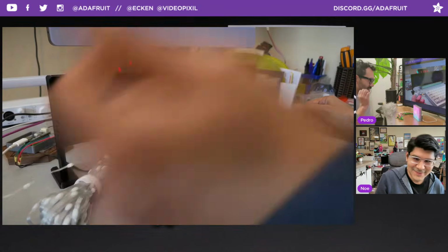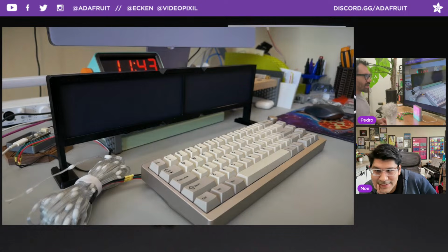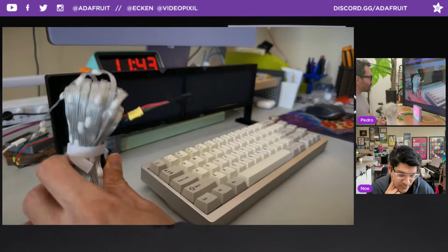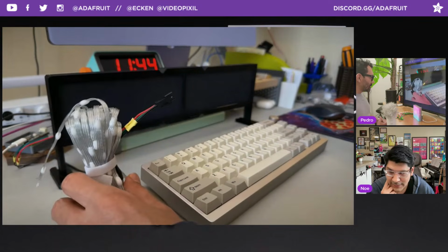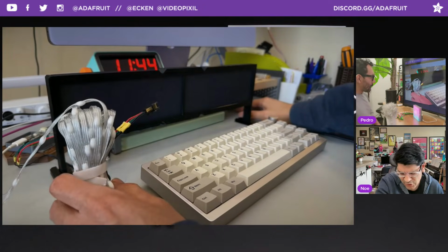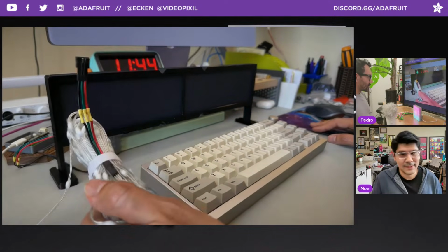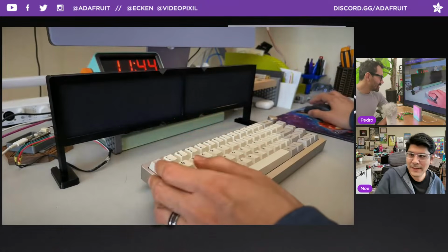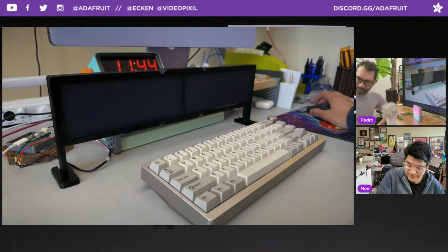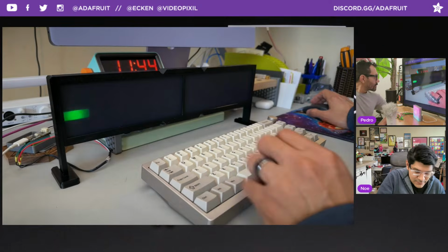I think this happened with the LED nets as well. Oh, really? So WLED has the ability to do that. Right. Okay. This is specifically with the NeoPixel CircuitPython library. It was just one line inside the library to add the ability to do BGR. So that was an interesting thing. Very strange. Weird that we haven't had pixels before that needed that update to the library. Not a big deal, but something to note. So now green is actually green and red is actually red.